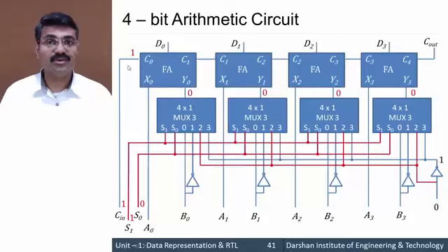So as per the formula D equals A plus Y plus C in, what is the input? A is fixed. Now Y, all bits are 0, so A plus 0, and C in is 1, so A plus 0 plus 1.